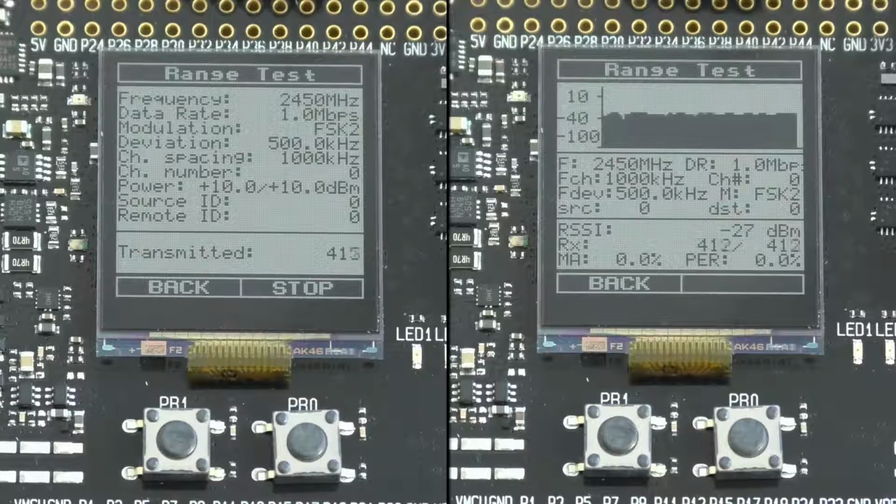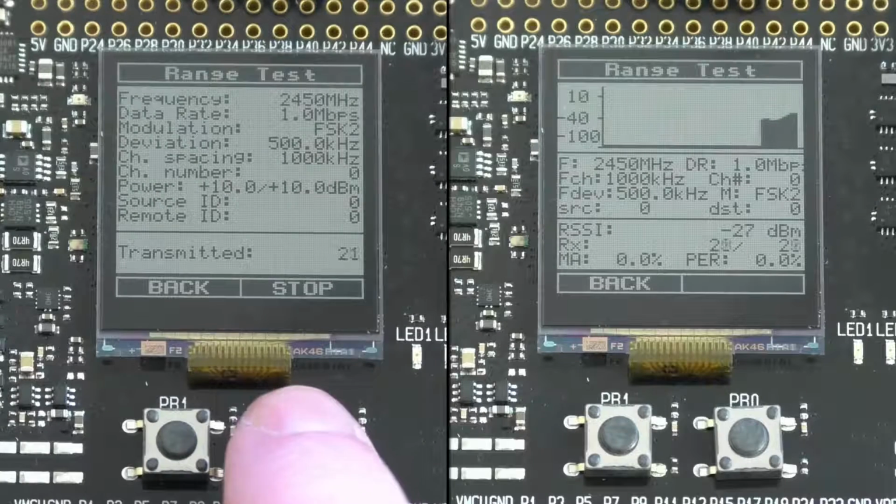The signal strength of the incoming packet is measured during packet reception and the actual RSSI value is shown on the LCD display. The RSSI values are also presented as a graph on the screen. The dynamic change in RSSI value can be observed accurately by configuring the moving average window size. The test runs as long as the number of transmitted packets reaches the predefined number or until the test is interrupted by pressing Stop at the transmit side.